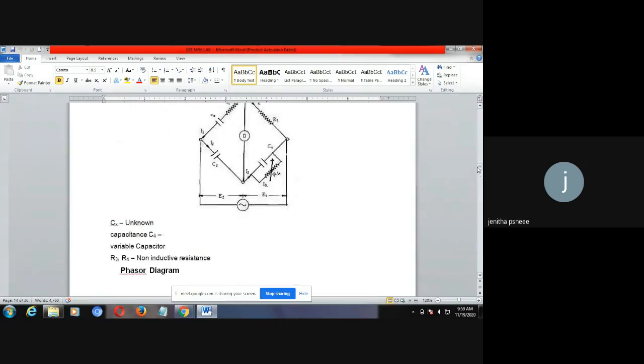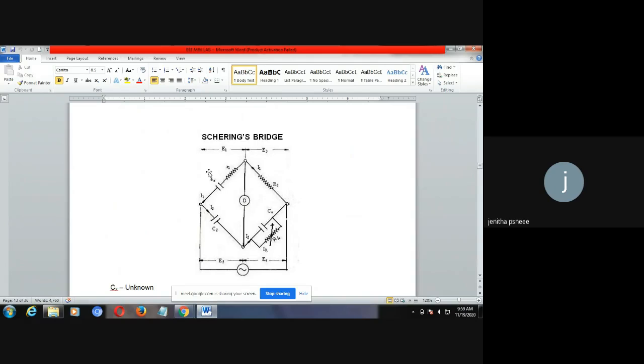See, so this is the unknown value, Ex, like that given. So in place of this value, if I keep 0.4, then this detector will show you 0. That means if you place the CRO, it will show you 0. And if you place any detector like headphones, the headphone noise will be stopped.